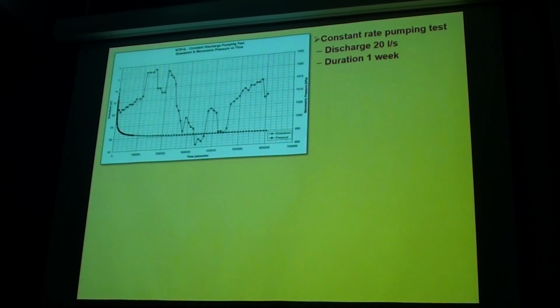And time across the bottom here, I graph these ones in seconds, because that's what we were calculating in, and it doesn't really matter as long as you keep your time units constant in all your calculations. You can see initially, over a very short time period, the water in the well started at 0, okay, and then we reduced it to proper RL, and then it takes a big dive, and when that's happening, you're sitting there holding your breath, hoping it doesn't keep going, because then you're stuffed, because your pump will shut down and you've got issues, you're not getting enough water out there.